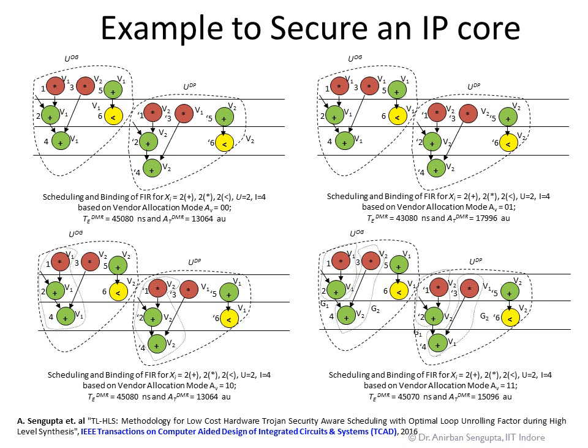Now, as you could see here, as a short example of an FIR, the operations 1 and 3, which are given to V1 and V2, have distinct assignments made for operations 1' and 3' by assigning them to V2 and V1. Similarly, distinct assignments have been made to operations 2 and 4 by changing them from V1, V2 to V2 directly. So as you could see, every sister operation from the original and duplicate unit has distinct assignments. However, how you achieve the distinct assignments also dictates the final latency and area. So that has been reflected in this slide.